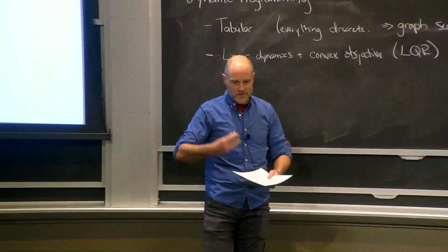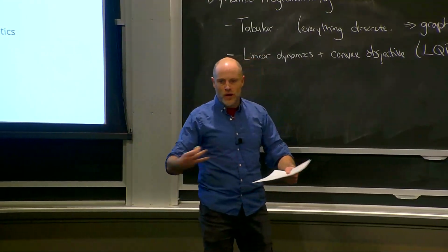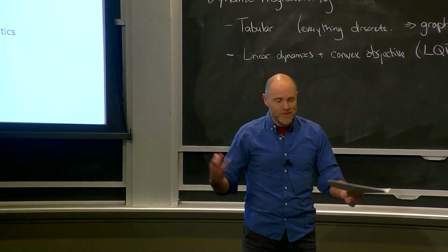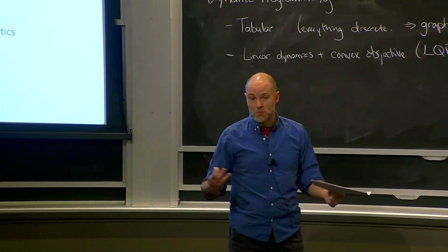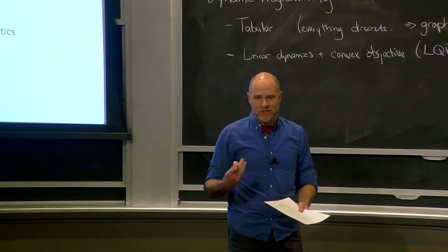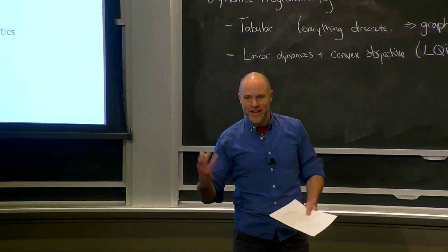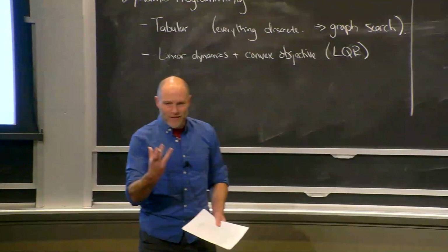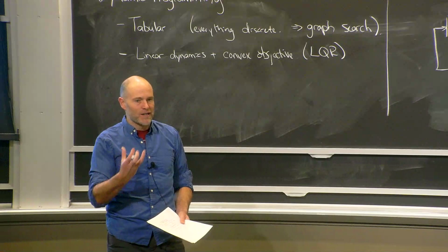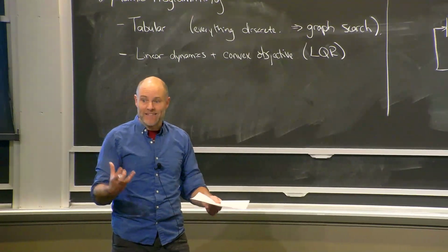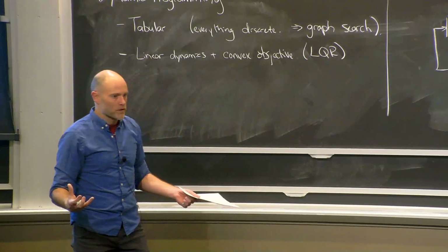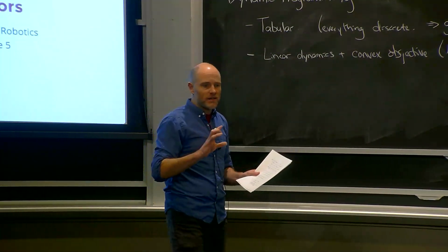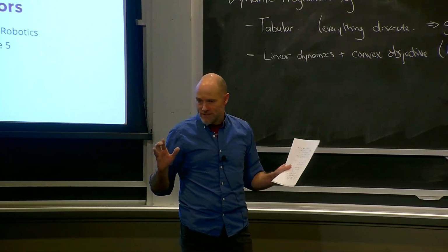This is not a new Drake thing. This is a Simulink thing, Modelica. Throughout history, the way people have architected very complicated systems is with the language of diagrams, block diagrams, right? This is like the same way object-oriented programming is very natural for some types of programming, functional programming for others. For dynamical systems, the block diagram, signals and systems abstraction is the one that has classically made that scale and work, where each little system can be written independently. It has input-output ports. It declares its state.